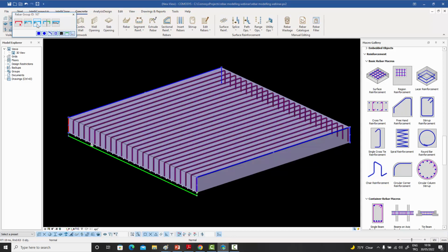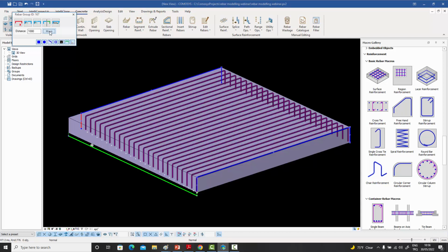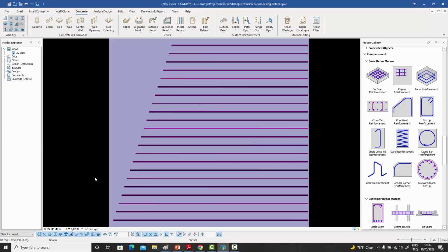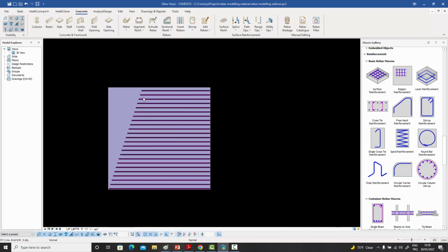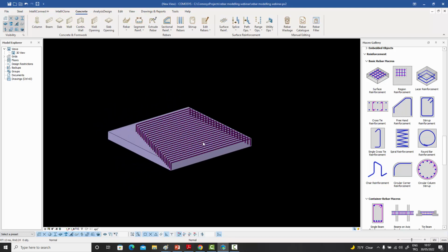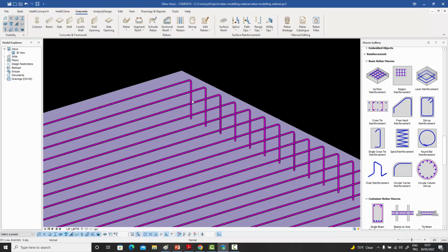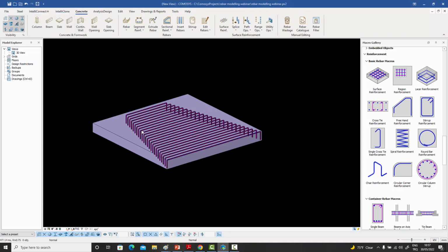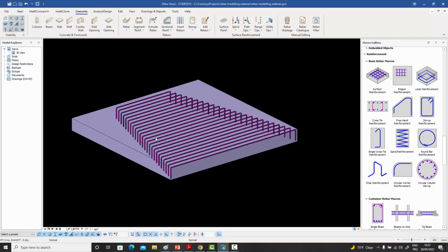So let's select this one and give it a move, let's say, of a few thousand millimeters. And immediately what you see on the screen is that your bar has become a tapered bar from the start to the end. And that was very convenient. I can do that with the edge, with the segment at the other end as well. I can go and I can make it move inwards as well. It's a linear tapered bar now, but there's more.